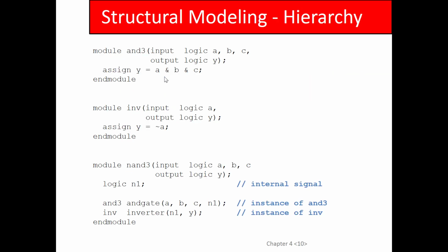And then let's take a look at a structural Verilog example. And this is actually, I think, most of you, having learned an object-oriented language right from the beginning, in CS1 or 145, probably are pretty comfortable with this idea, but you just have to think of it in terms of hardware now. You've got an AND gate, you've got an inverter, and then I want to instantiate an AND gate and instantiate an inverter in this more abstract module and then connect them. But the one thing that might be new is the connections are made through internal wires.